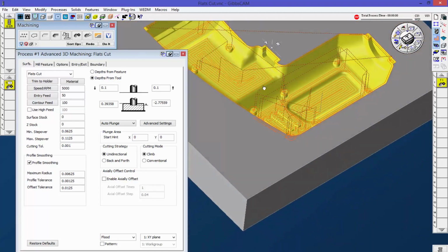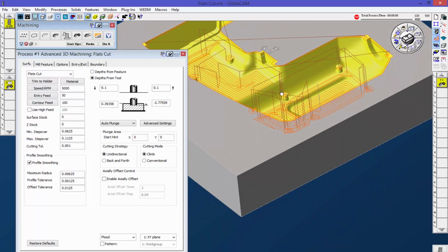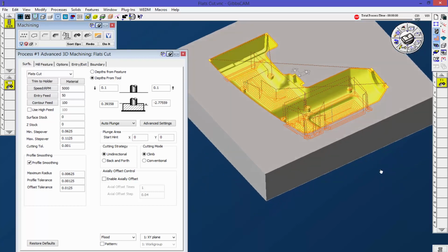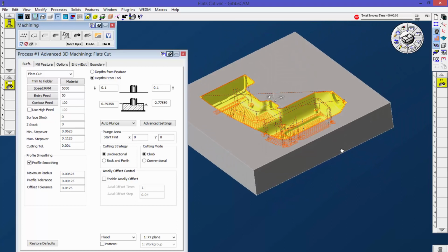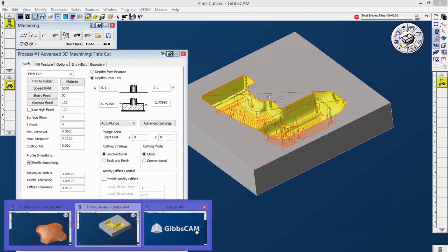So if I had put in a step over toolpath, whether it was a constant step over or a lace cut or an end curve flow, and I ended up with a bunch of scallops on these flats, I can just go in there with an end mill and then clean up those flat surfaces. This also works really well on the opposites of this, so on the core part of this, and I can show you that right now. Let's go ahead and open that guy up.